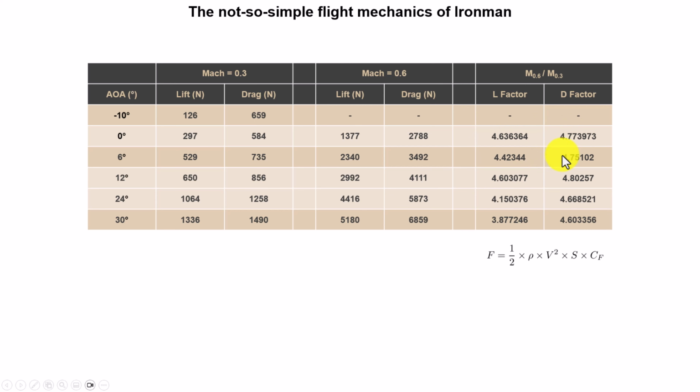You have it here, roughly speaking, and you start to see that at 30 degrees it starts to go down, because we start to see non-linearities. I know that at Mach 0.6 I already have some local regions where the Mach number is more than one, and that creates problems. But this is also not from aerodynamics. We know that behavior, we have it there.